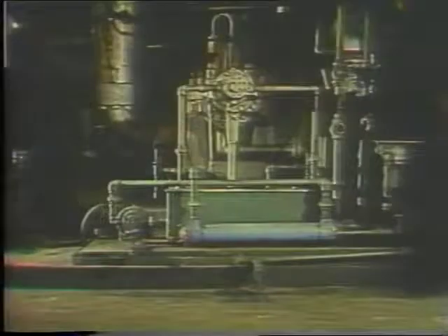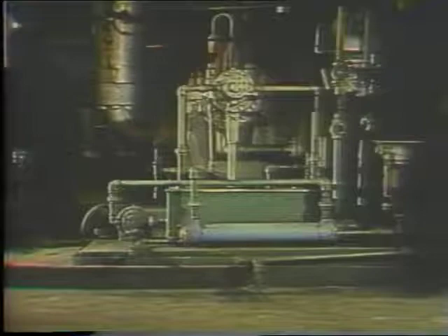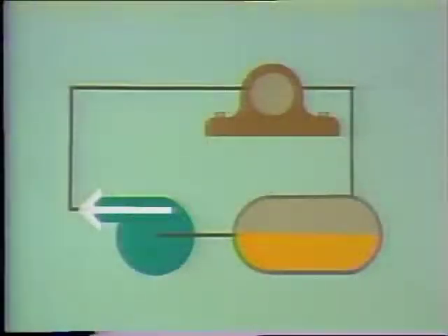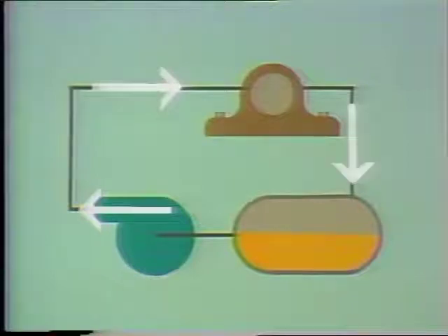The forced lubrication system is another type of system that we should discuss. A forced lubrication system continually circulates a steady supply of oil through one or more bearings. In this type of system, there is a pump that pushes oil into the bearings, and it's usually collected in a reservoir so that it can be pumped through again.